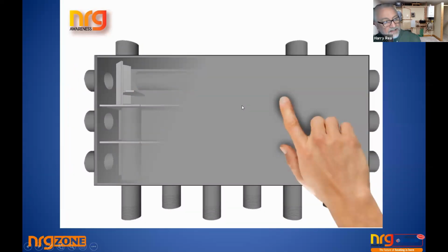One very critical thing is, by simply touching, you'd want to be careful not to have a solid fuel boiler at full burn. But if you were sensing what's going on in the system with your bare hands, you can actually touch the flow chamber, the bypass chamber, the return chamber. You can catch any zone. So if you have something wrong with a valve or a zone pump or whatever, by catching the zone pump's flow and return, you can see straight off that the water is flowing in one circuit better or not than another circuit. So straight off, within seconds, you're identifying there's something potentially wrong. So for fault finding, it's literally at your fingertips.